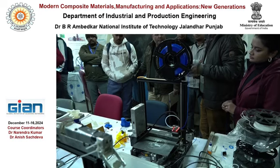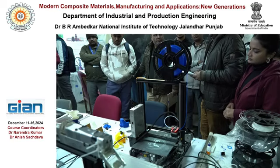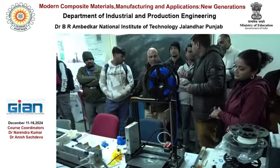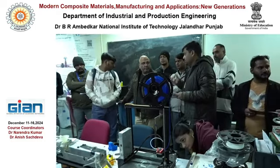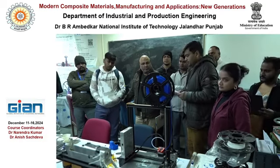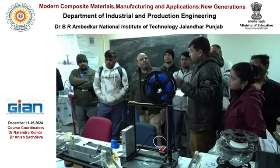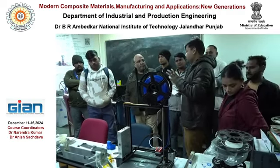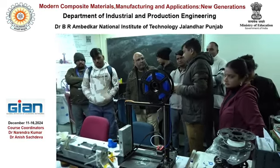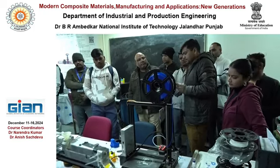So we have ABS, we have ABS conductive, we have PLA, we have the TPU also. TPU basically is a flexible polymer, an elastomer, so that you can print because you want to have some flexible properties. So you can easily make it through this. Then PVA is a sort of water soluble material. Suppose you want to use a support material, and that should be water soluble. So you can use PVA.